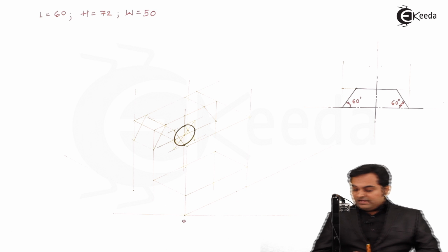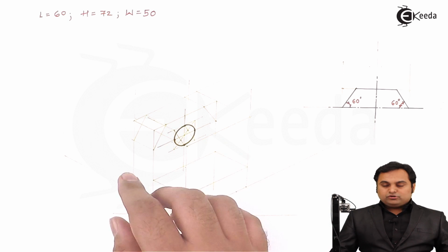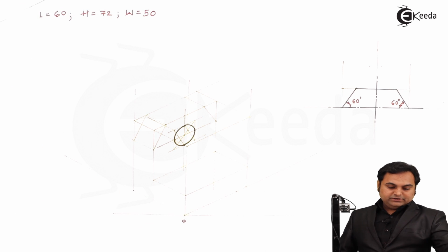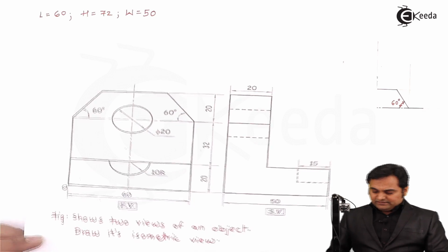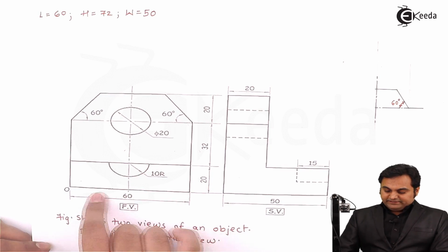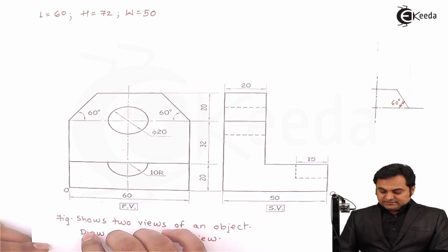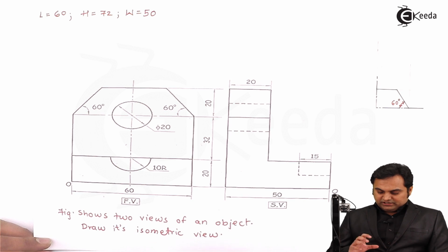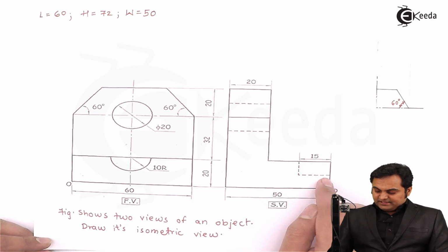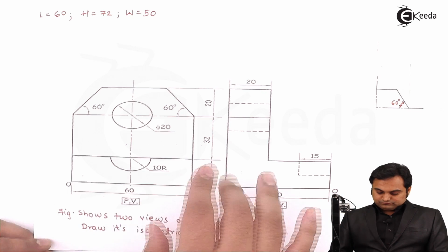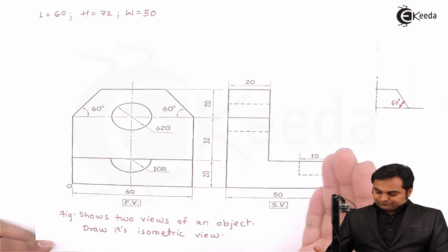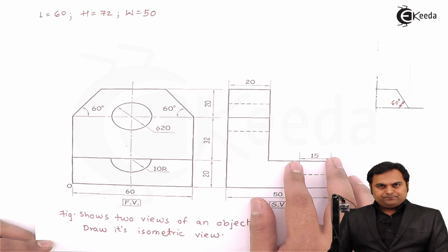So it means we have to leave this circular hole as it is, and it will be understood that this hole is throughout. Next, after completing up till here, I can see that inside this bottom plate there is a semicircular hole or groove which is cut, as it can be seen from the side view. That semicircular hole is up to a width of 15 mm.